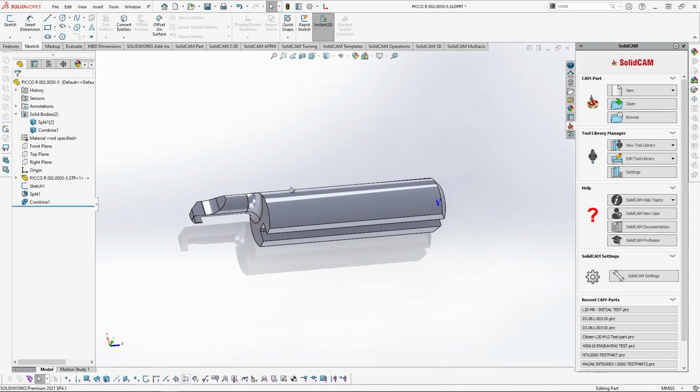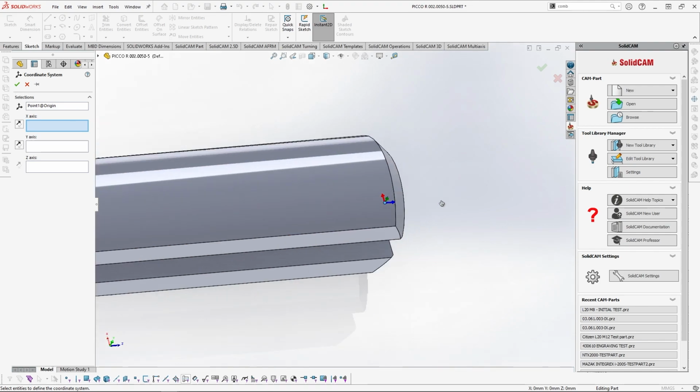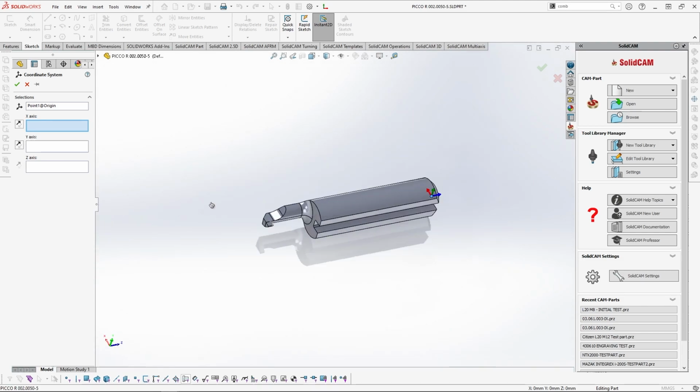Right, so let's start with the first step. The first step is to create the coordinate system of the shank. I'll go and create a coordinate system here, and it's completely fine to stay there. The orientation is correct, according to the one in the corner, and this one over here is in the middle of the shank. That's okay.